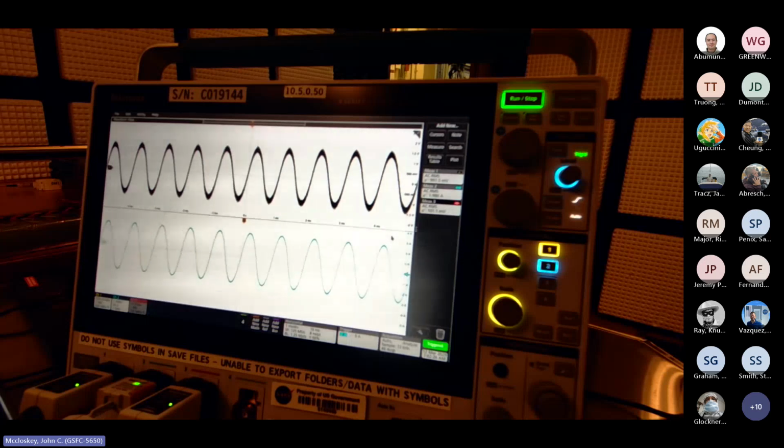Just because of my own, whatever you want to call it, OCD or anal compulsive tendencies, I always would rather be just a little bit above the desired reading. Like you might say 997 millivolts is just fine, but I'd rather be above. And that's another setting in your control loop where you can set the tolerance. And we usually go with minus 0 dB and plus however much, plus 1 dB or something like that.